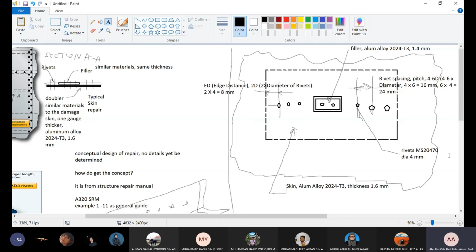The third stage will be testing the strength. You check the shear stress, you check the tension stress, you check the buckling, crippling of the repair plate, plus shear of the fasteners, bearing on the holes of the fasteners or the rivets, and also the net section tension, tension failure across the plate, and tension to shear out from hole to the edge.